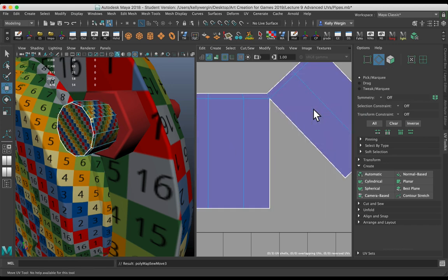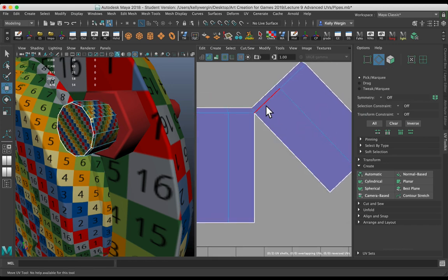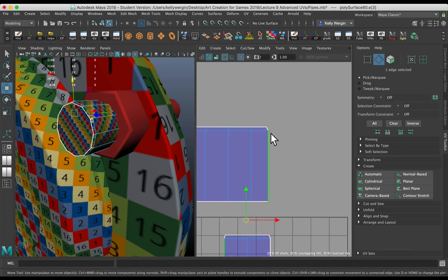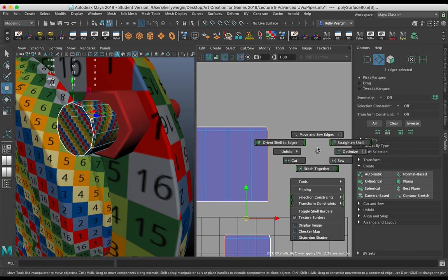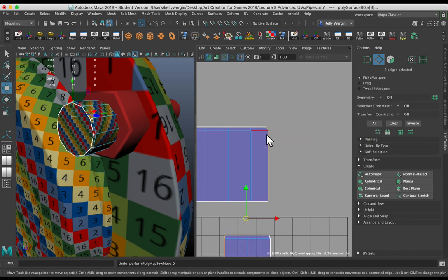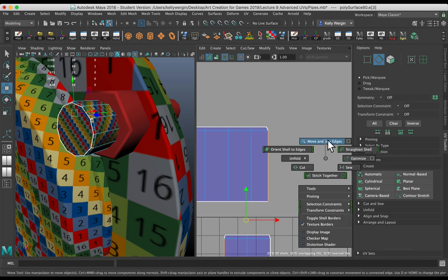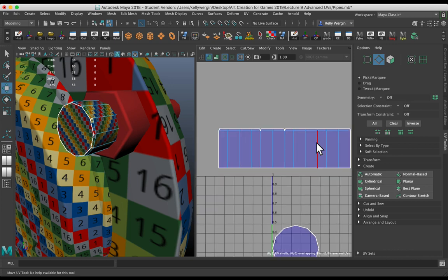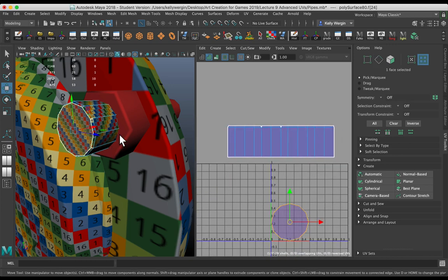Grabbing the angled bevels and moving and sewing is going to sew it crooked like this. So if you have straight edges, even if I then grab the bent edge as well, it's going to sew on more straight than if I just grab this. Now it's going to be better if I just grab this here and sew it, and then take this edge and shift right mouse and sew it. I might not even want to sew those together. I would need to double check and see if they're tapering. And then I have the cap here.